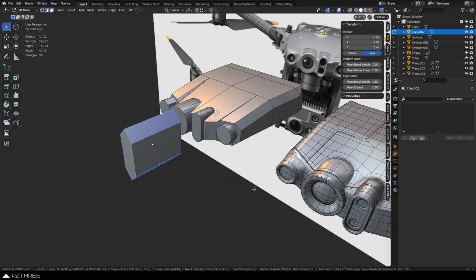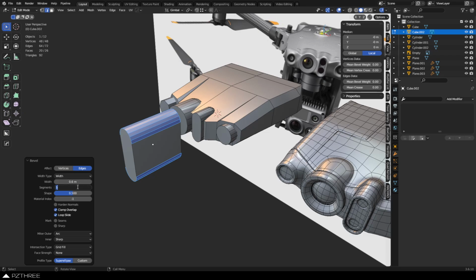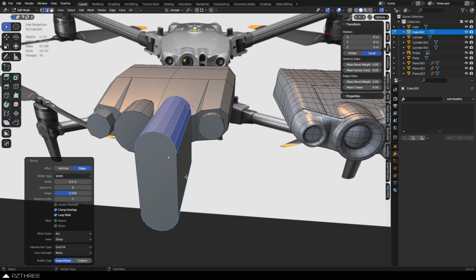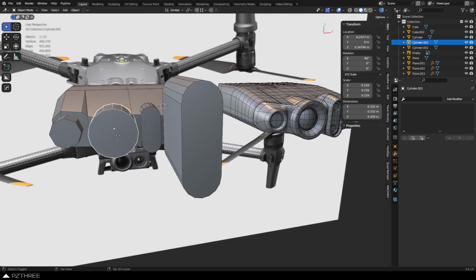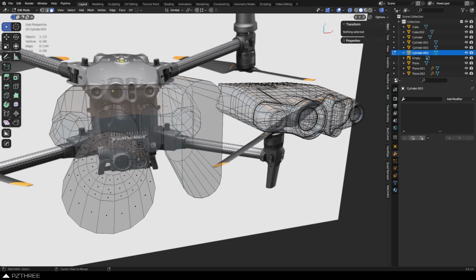So you hit C, clamp it, and you mouse wheel up, and you want to use even amounts here as well. So something like 2, 4, or 8 usually works out well. And this is so you get a center vertex and a vertex on the right and a vertex on the left. This is the same idea as a cylinder that's been split apart.